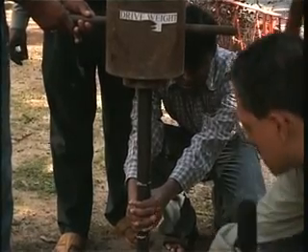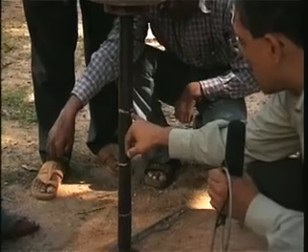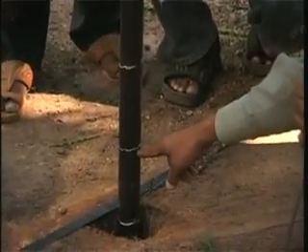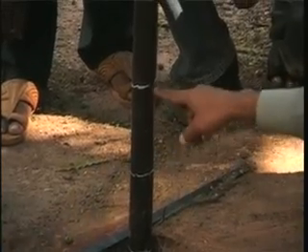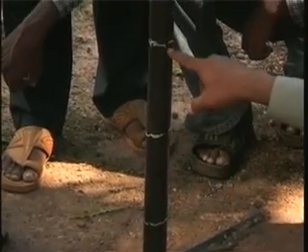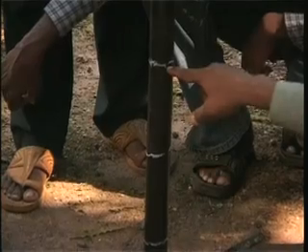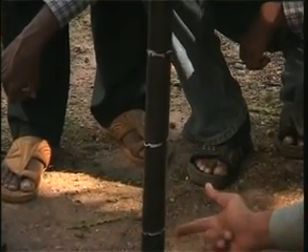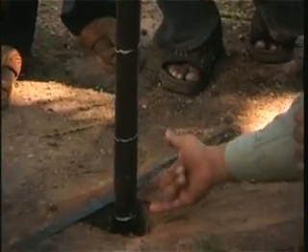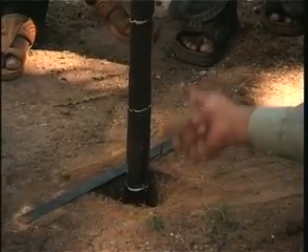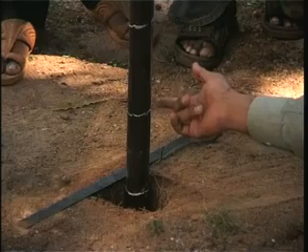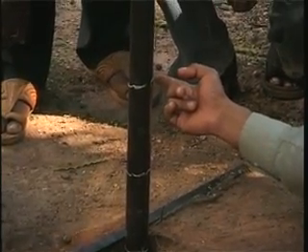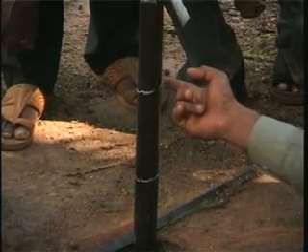And what you also see is that we have got three markings at 150 millimeter spacing, one at the top of the hole, then 150 millimeter above, next one 300 millimeter above, and the third one at 450 millimeter above the top of the hole. So what we are going to measure is the number of blows required for the penetration of this length from here to here, then the number of blows required for penetration from here to here, and finally the number of blows required for penetration from here to here.